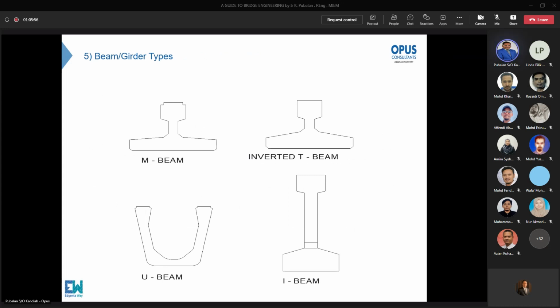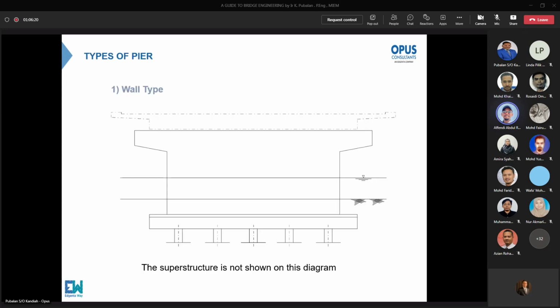If it's a U beam, I'm still okay with it, because U beams are normally quite big. But Penang Bridge, we don't have U beam. On the original bridge, if you have I beams and all, then the beam is broken already. So your parapet is good, but your beam is broken. So you cannot. In this case, you need to go back to the owner of the design.